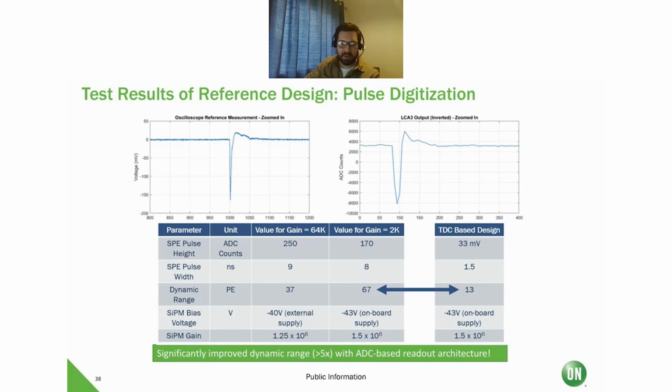But I think the key takeaway here is the significant increase in dynamic range when using the ADC-based approach. So we have a significantly improved dynamic range. It's nearly 5 times improved when using the 2K gain setting in the ADC-based approach compared to our TDC-based board.